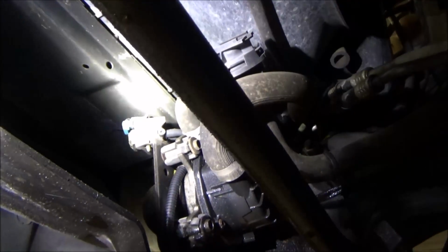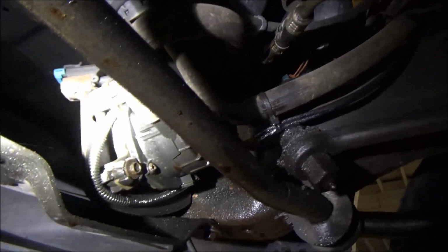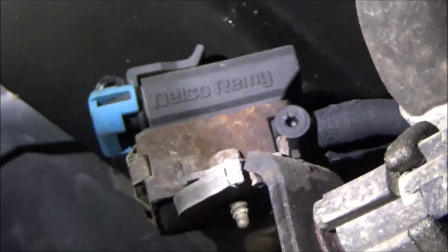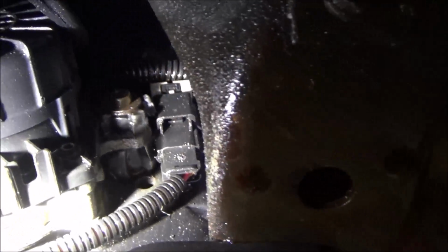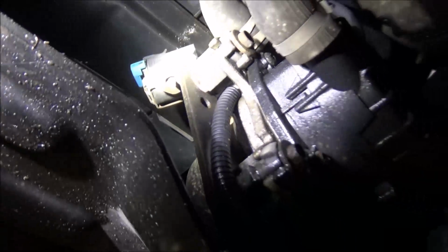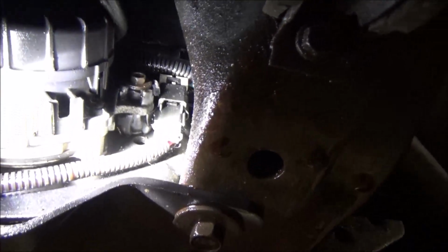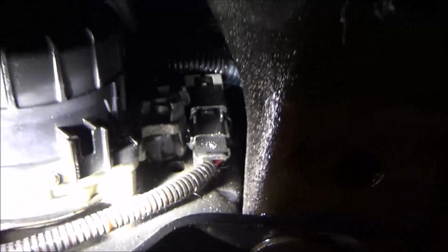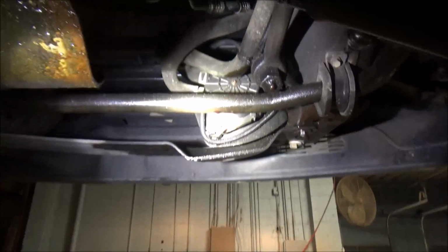I realize it's pretty tough to show you this, guys, but I'm going to see if I can get a better light after this. But if we look at this unit, we see that there's a wiring harness coming off of it here. We can see right here we have a vacuum solenoid. And I'm just looking over this motor, guys, and I'm trying to find the actual motor connection. And it looks like this is it here. There are some heavier gauge wires going up to this. And it looks like it just comes off of a pigtail and plugs directly into the motor right there. So as far as our test location for this motor, it's going to be this harness connector here, guys. This one right to the right, this being the front of the vehicle, just for perspective.